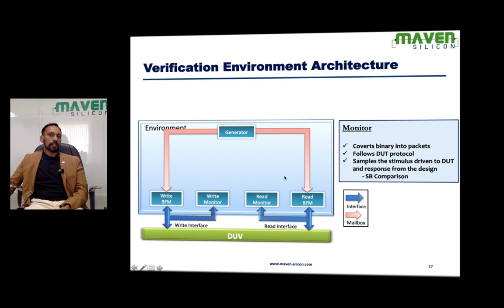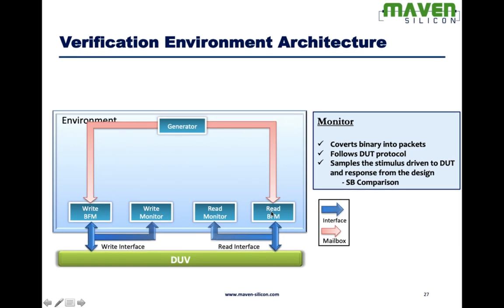The same thing happens for the read interface. Read packet will be sent to read driver. Read driver converts the packet into binary values. When it drives the binary values based on read protocol, all the binary values will be collected by the monitor and it produces the same packet back. But in case of read, there will be some output data also from DUV. So this read packet will be different from the driver packet. It depends on the protocol. All right.